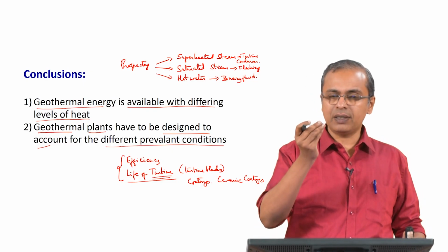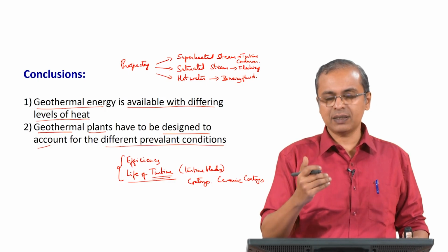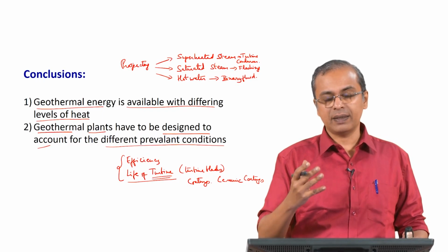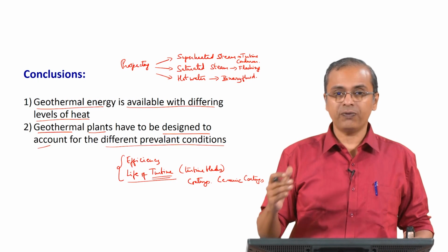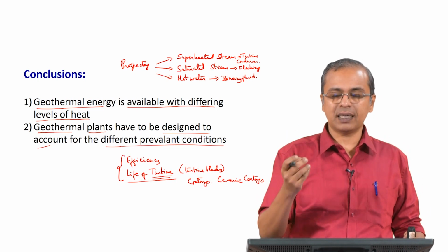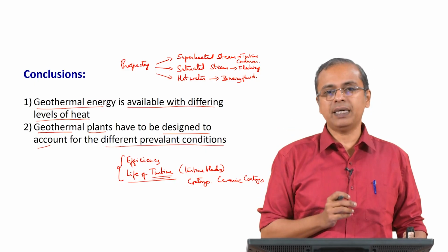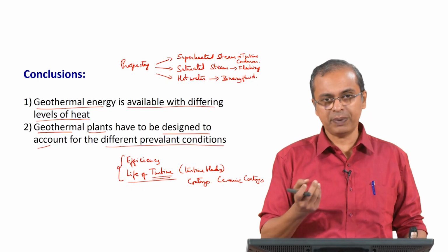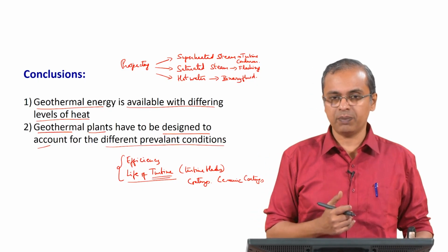Even if the actual blade sees a temperature that is 5-10 degrees lower than the temperature of the gas that is hitting the turbine blade, that itself would greatly increase the life of the turbine. On top of it, if there are any particles that are coming by chance from underground, which you do not have control over, the ceramic material will take the impact from those fine particulate materials that may be present, and that again helps protect the turbine blades.